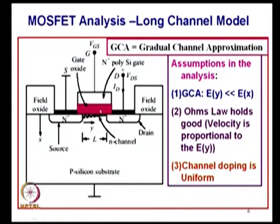Okay. And when you analyze this, you will actually not bother about the entire region. Your focus will be only on this portion, because that is the portion which gives you the MOSFET action. Okay. And these are the thick oxides which allow you to isolate one device from the other device in the integrated circuit. So, if it is N channel device, you use p type substrates, okay, and while analyzing you have some simplifications done.